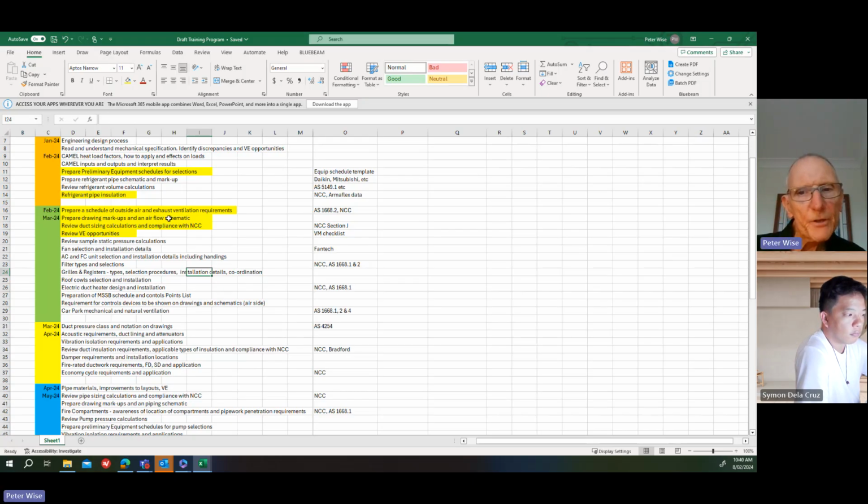And I'm just saying this now because I think it's relevant to the work you're doing with the heat loads. But it needs to be positive or negative, depends on the type of space, right? Like storage room, exhaust systems, it should be a negative type of space. Yes. So if it's, let's say, an office space, generally you'd aim for a slightly positive pressure because you want to stop infiltration coming in. So if you have a positive pressure, there's a bit of leakage to the outside, which stops the unconditioned air sneaking into the building.